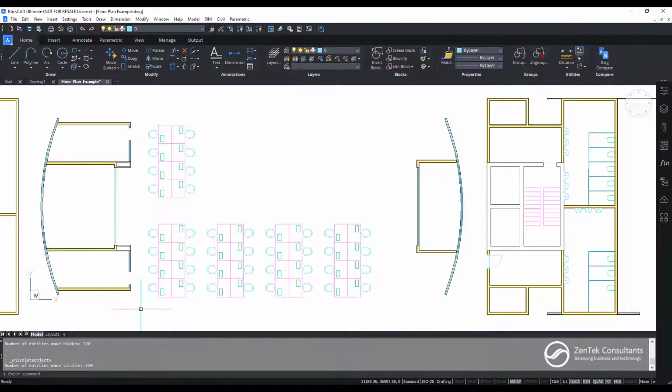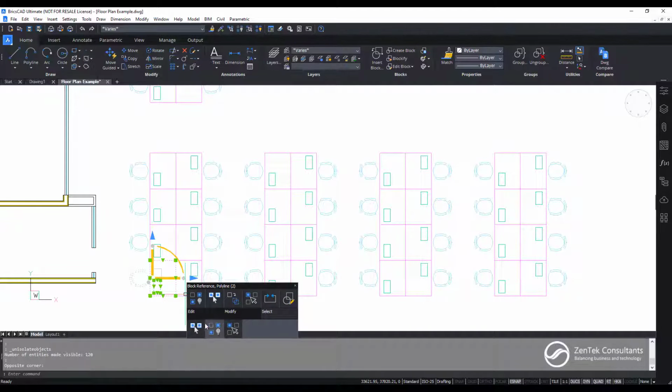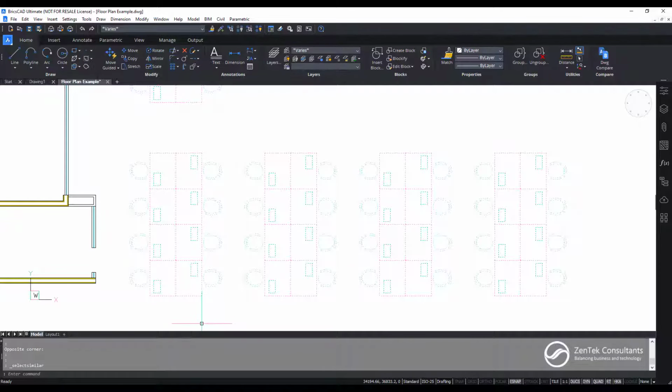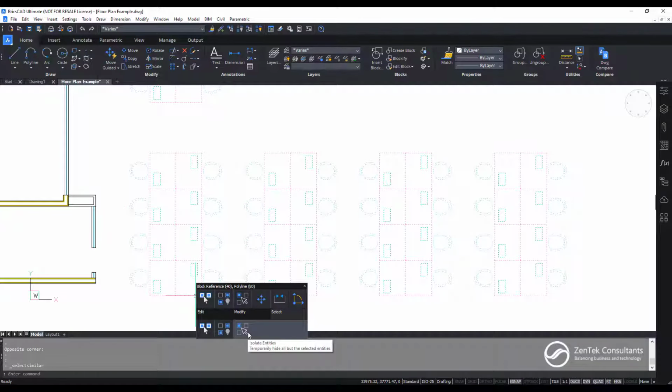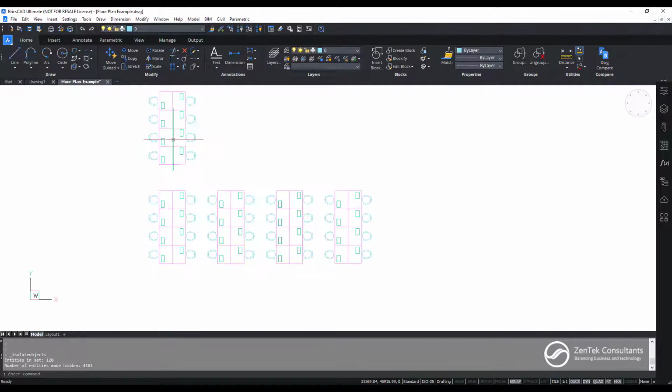Right? I can do the same thing by going in, using my quad tool to select my entities. Right? I can go back in again, select similar. Okay, see I've got those all selected. I can kind of do the reverse. Instead of hiding those entities, I can isolate them. Maybe these are the only things that I want to see. And now I've isolated so I can focus on working with just the items that I want to work with.